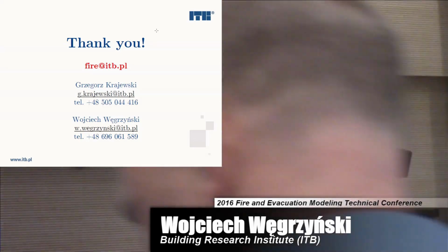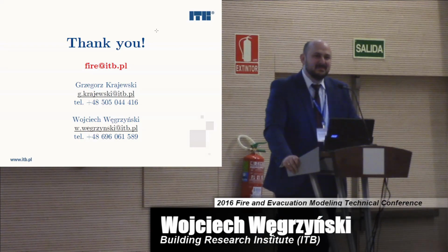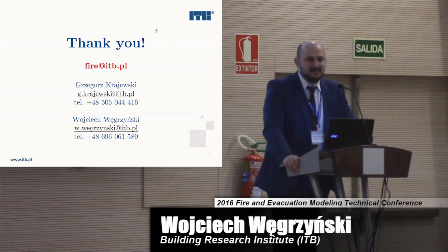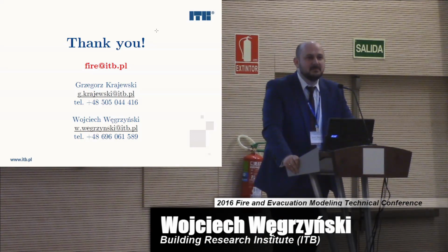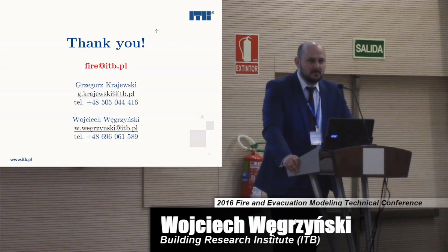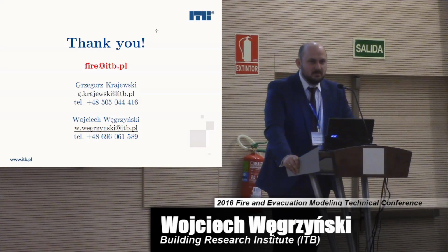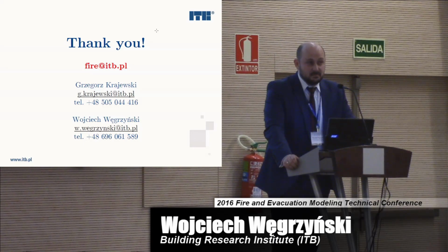Thank you for the presentation. It was really, really nice. And you're uncoupling the wind simulation from the fire simulation. How are you introducing the boundary condition from the wind simulation into the FDS simulation? Are you using a volume, or are you just introducing pressures over the ventilators?